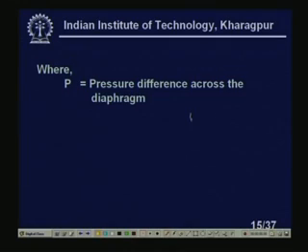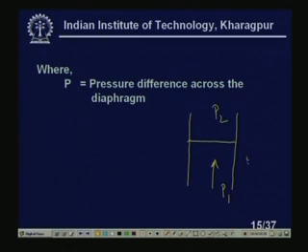Now, the diaphragm looks like this actually. They have a stretched diaphragm, right. Suppose this is P1 and the pressure on this side is P2, with P1 greater than P2. So, this diaphragm will be stretched like this, right. This center point deflection, you can sense either using an LVDT or some force strain gauges. That is calibrated in terms of pressure, right.